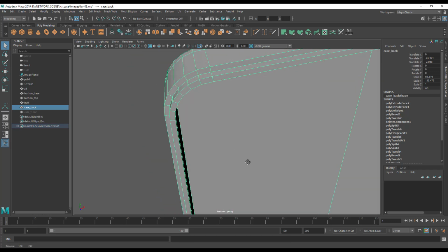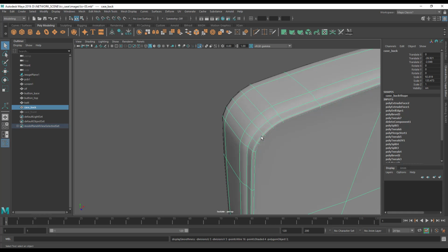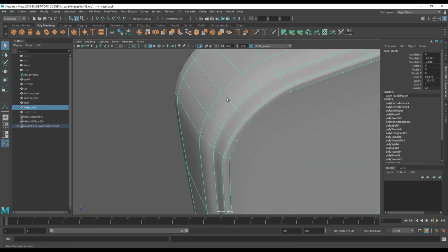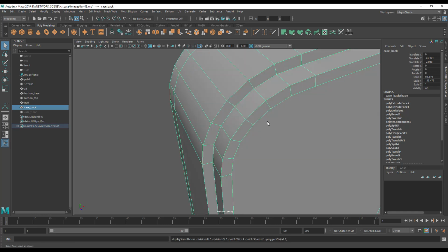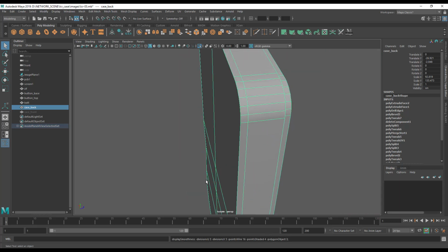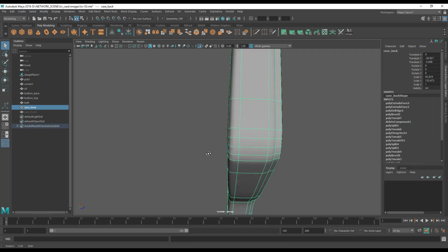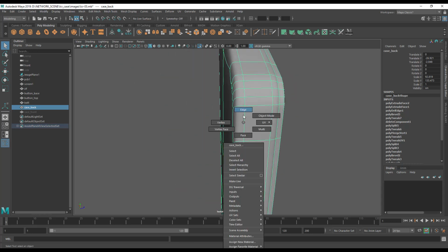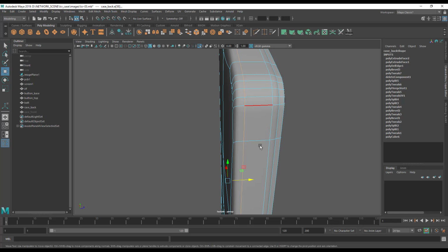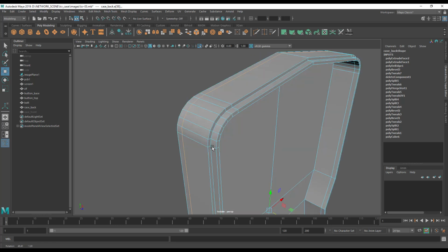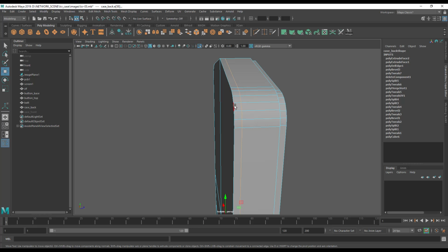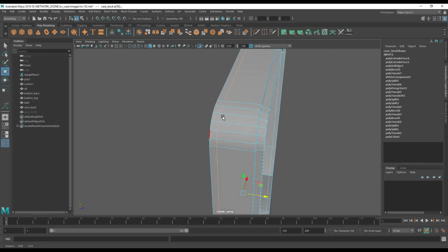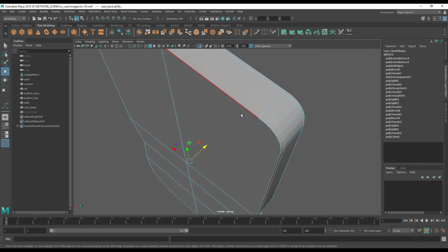So I'm going to come up and I'm going to look at what happens when I smooth the side of this. Now this is completely useless. Look, absolutely useless. Those will no longer fit together in nice straight lines, so we need to fix that. Also, the back of this thing, when smoothed, is... actually, it's not bad. We could move this edge here to create more of a bevel at the back, but I really don't like that way of doing it, because what's going to happen is it's going to change the thickness of this thing here. So we want this to always be 2mm thick.